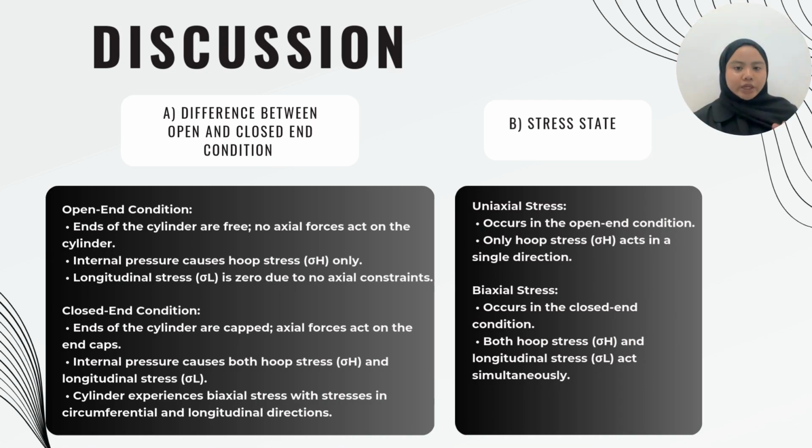For question 2, which case experiences a uniaxial state of stress and which case experiences a biaxial state of stress? The uniaxial state of stress is experienced in the open-end condition.